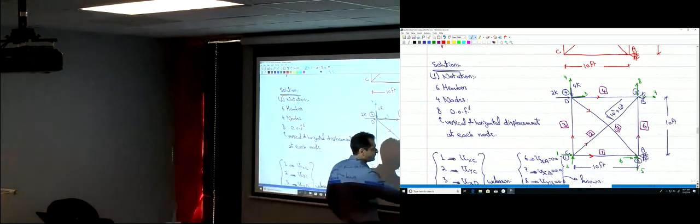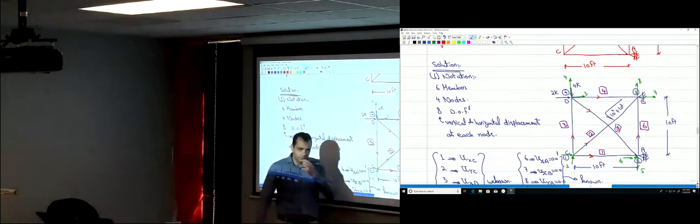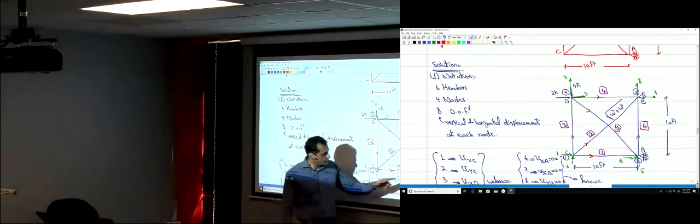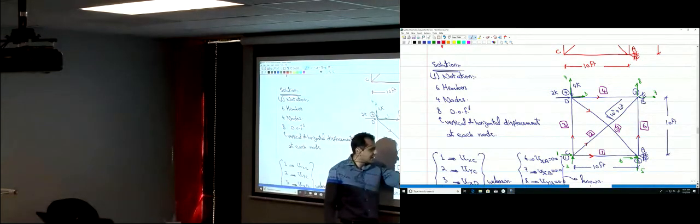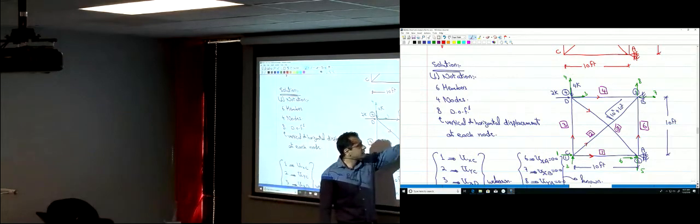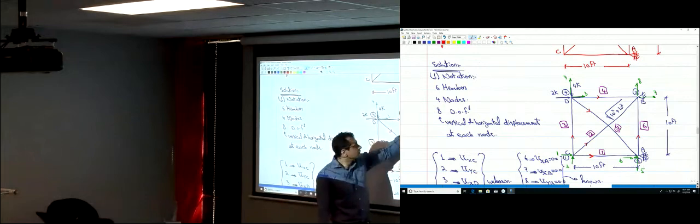The force here, the horizontal degree of freedom. What does this represent? The reaction, the horizontal reaction of that support, AX. How much is this? I don't know. The 7th, it's what? BX. The 8th, that's BY. Okay? Those are unknown reactions.